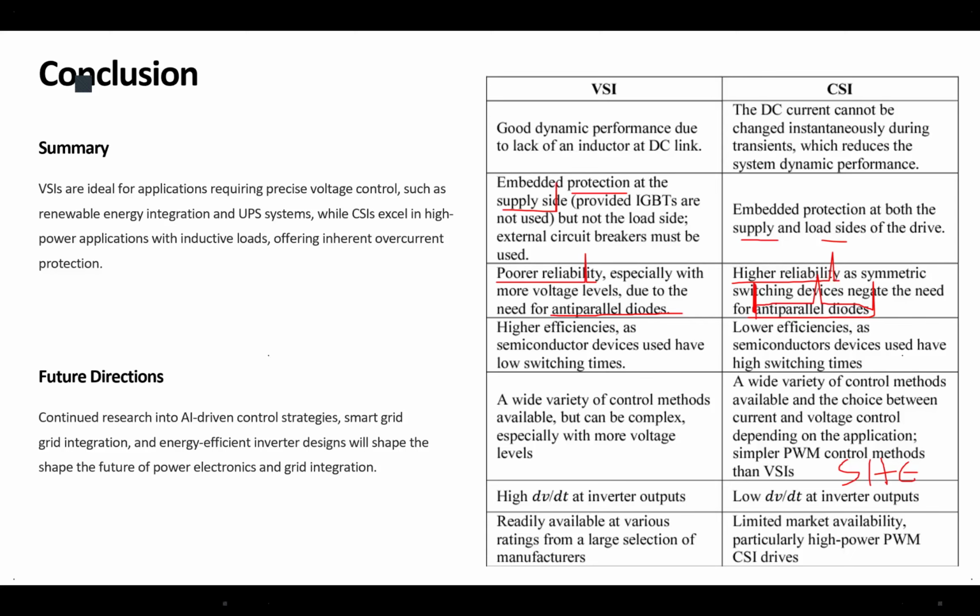But if you connect it to the CSI, because of the control technology in the CSI, we are going to talk about the control system later in the session, the control algorithm of the CSI does not allow draining a huge amount of current. So it would limit the current. Ergo, it would limit the higher spikes.